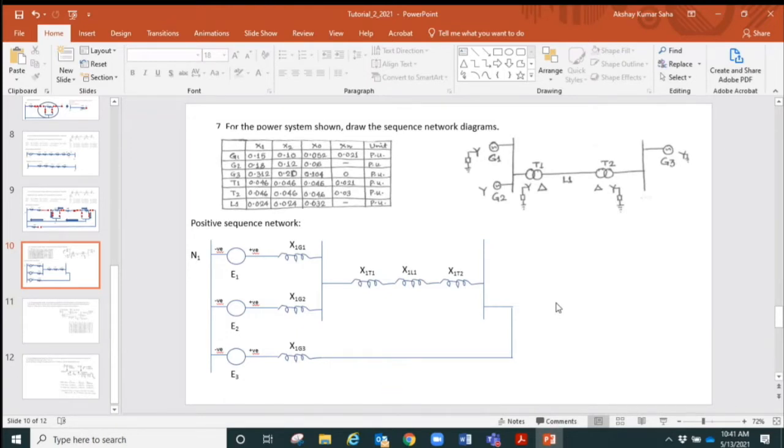Sometimes the diagrams look a little different, because like this one, I drew the neutral bus vertically for all of them so far. I could draw it horizontally as well, and then the system sequence network diagram will come down vertically as we go along, from the generator to the transformer to the line to the second transformer to the last bus bar and the generator.